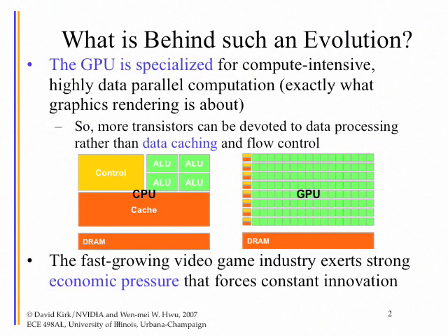parallelism. So when people design a typical CPU, the CPU would look like a piece of control logic with some ALUs, typically about 12 to 16 function units for a CPU. And then there will be a fairly large cache. And this cache memory can be organized into hierarchical arrangements. The first level cache is typically about 16K bytes, and the second level is about 256K. And the third level right now is between 1 meg and 9 meg, for these machines, just so that you get some concrete feeling about these things.